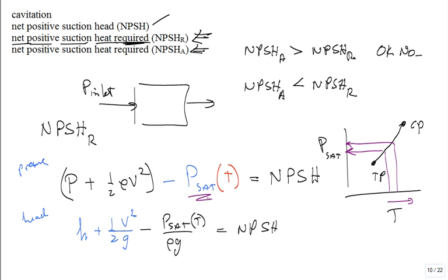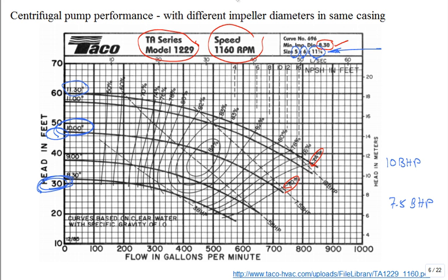All right. I think let's go back to the plot, the pump performance plot. Now finally we can understand this net positive suction head in feet. But where is that information? It's hard to see. But this right here is a line of 16. This is a 10. This is 6. This is 4. So what you're supposed to do is take those lines and just kind of extrapolate down. Okay? So if your pump is to be operating anywhere on this line, right here, here, here, here, you need 4 feet of net positive suction head. That's what's required. You better have more than that available, or you're going to have cavitation. If you're operating the pump out in here, which would be pretty extreme, to avoid cavitation you have to have 16 feet of net positive suction head.